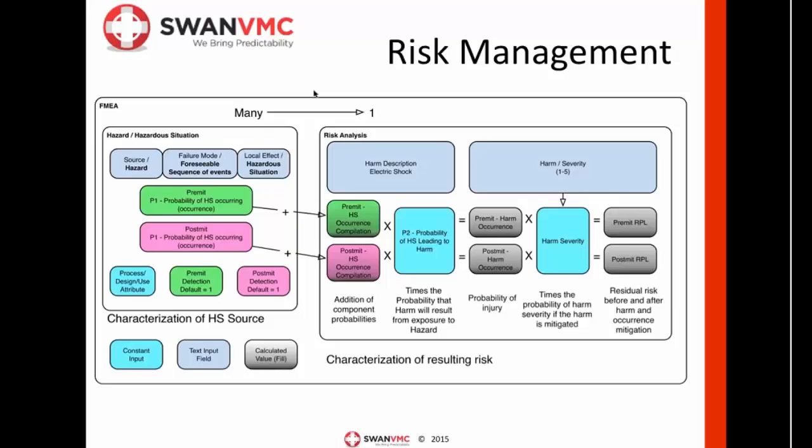So how likely is it that not only that the wire gets nicked, but then it gets pushed over and actually touches the case and the thing's plugged in all at the same time to create the situation where we have an energized case? That's what the P1 factor is. And then, of course, because we have 2 different or 3 or 4 different hazards, that P1 factor has to be added up. And now, of course, from a statistical standpoint, the worst case is adding up these probabilities.